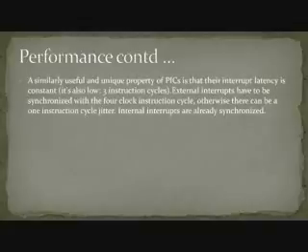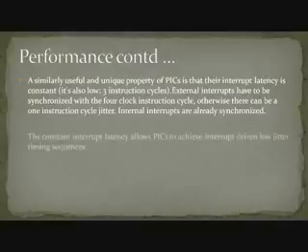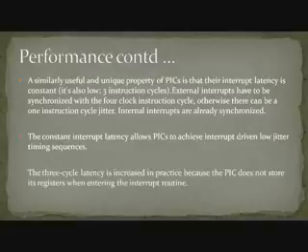A similarly useful and unique property of PICs is that their interrupt latency is constant. External interrupts have to be synchronized with the clock of the instruction cycle, otherwise there can be a one instruction cycle jitter. Internal interrupts are already synchronized. The constant interrupt latency allows PICs to achieve interrupt-driven low-jitter timing sequences. The 3-cycle latency is increased in practice because the PIC does not store its registers when entering the interrupt routine.